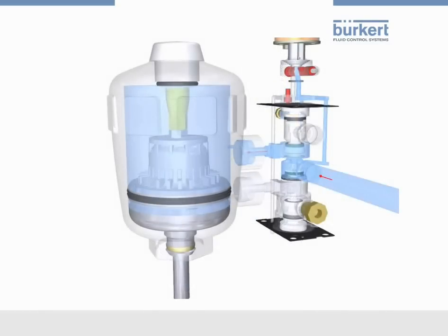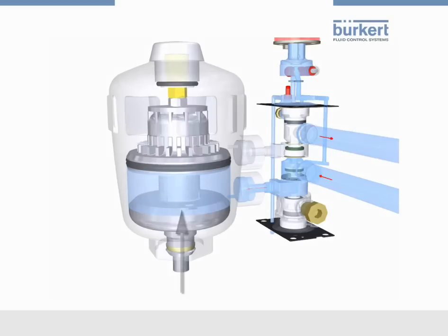In the original state, port 2 of the Namur valve is connected with the upper connection of the process valve. Compressed air fills the upper chamber of the actuator. If the Namur valve switches, this chamber is vented via port 3 to the atmosphere. At the same time, compressed air gets into the process valve via port 4 and lifts the piston.